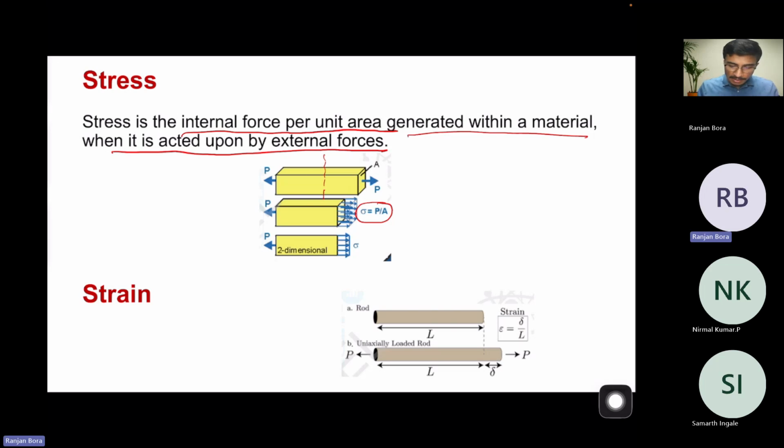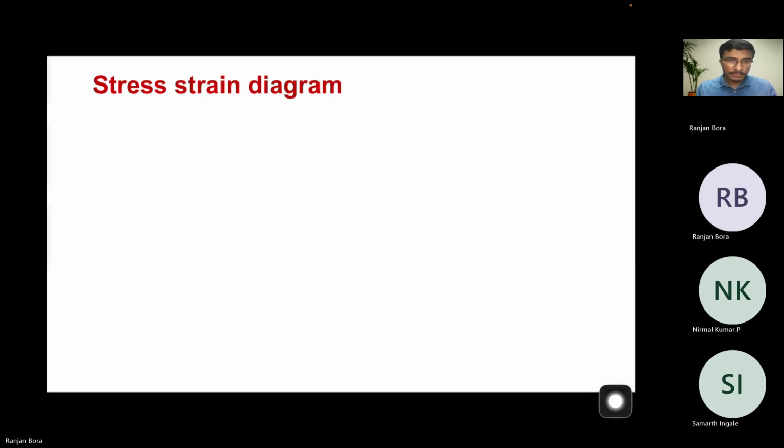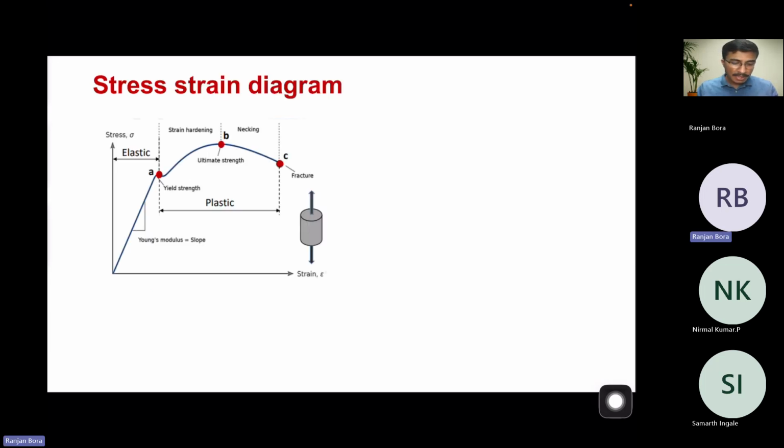And strain is when we are applying the force P, its length will increase because of the applied load. So strain is the change in length divided by the original length. Now, stress strain diagram.